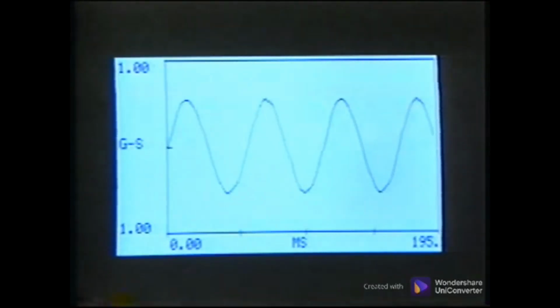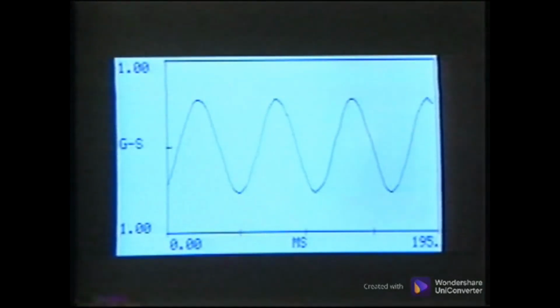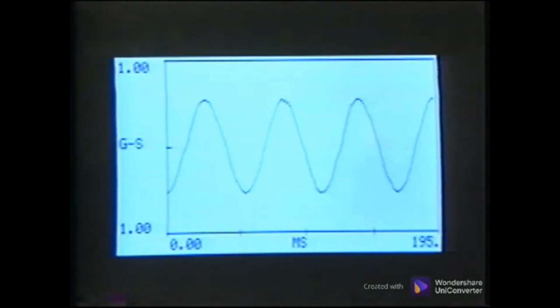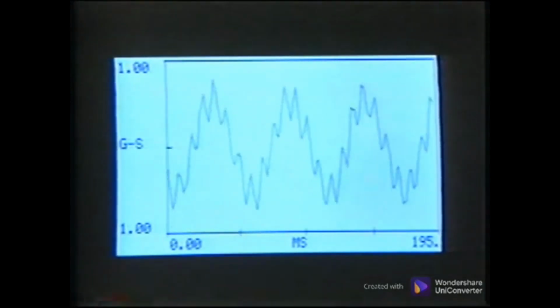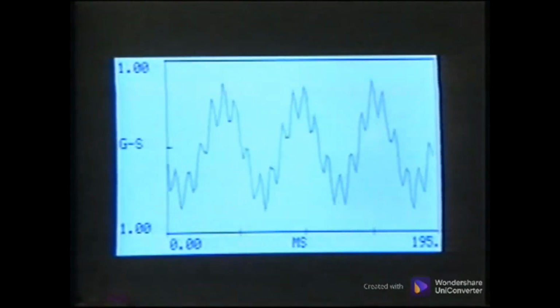The second signal is from a signal generator. The input frequency is 20 Hz and is a smooth sinusoidal waveform. The two signals combined show the amplitude variations as the signals add and subtract from each other, creating a more complex time waveform. This example showed the waveform data in acceleration.